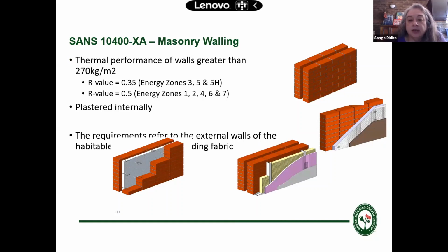So Kieran, you're right, and that's why we still give a performance value for walls, because the constructions you're talking about, common in the UK, Germany, France, use combinations of wooden construction, and when you add them together, they have the right performance. So when I say don't fill a cavity, you can fill a cavity with insulation.